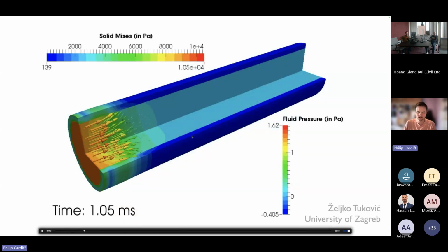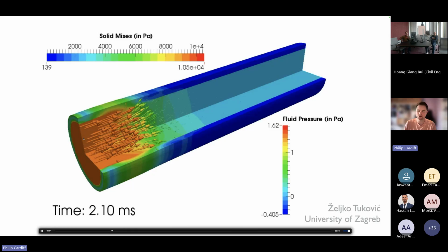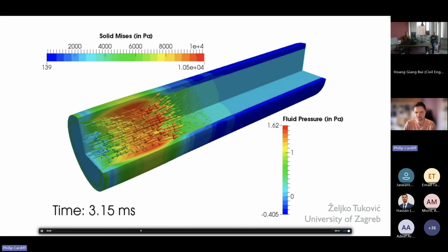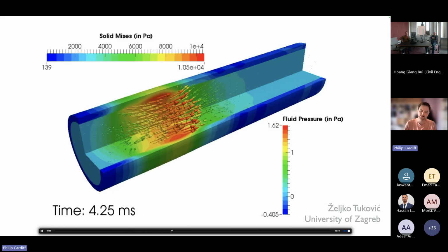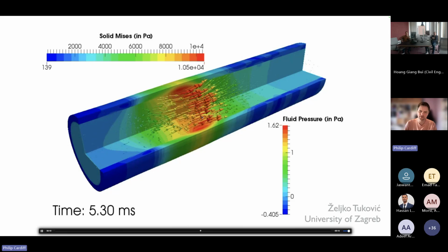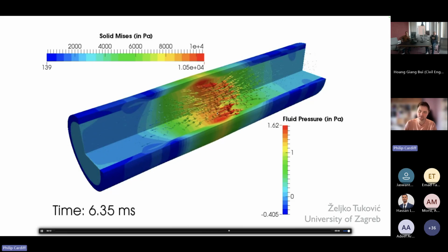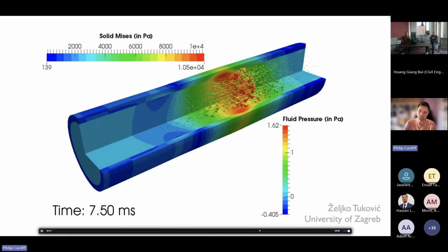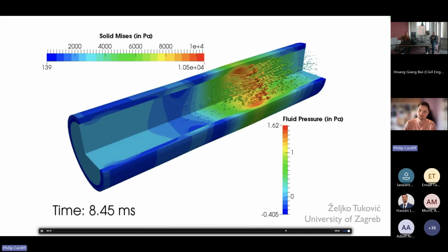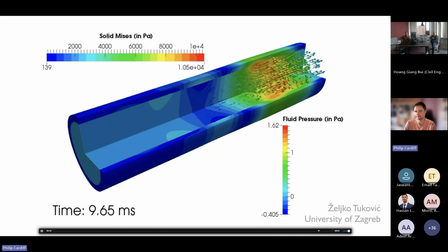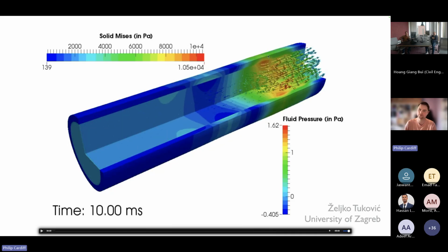And then this water hammer test case, a pressurized pipe where you apply a pressure pulse and it travels down the pipe. Even though the fluid is incompressible, so the speed of sound is infinite in the fluid, you actually get a moving pressure wave in the incompressible fluid just because of the finite speed of sound in the elastic wall, basically. So this is often a starting kind of benchmark before you go to, let's say, cardiovascular flows.